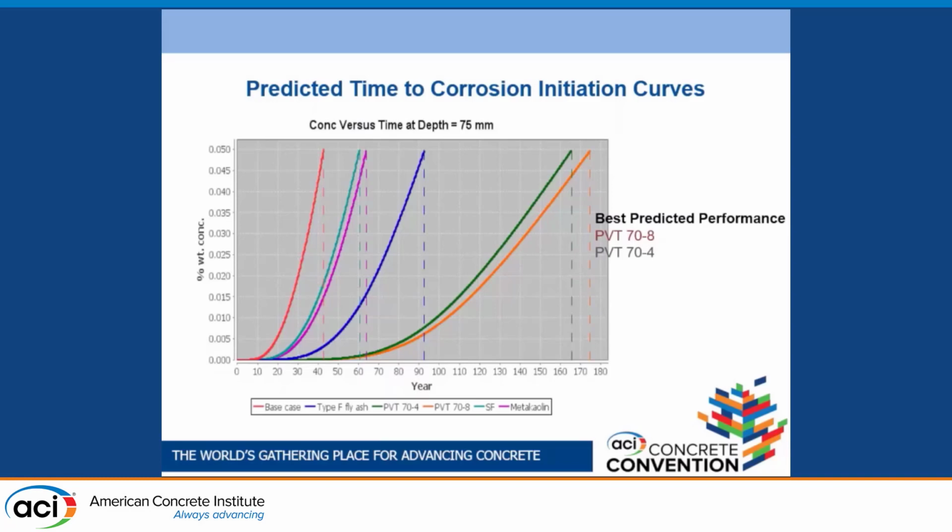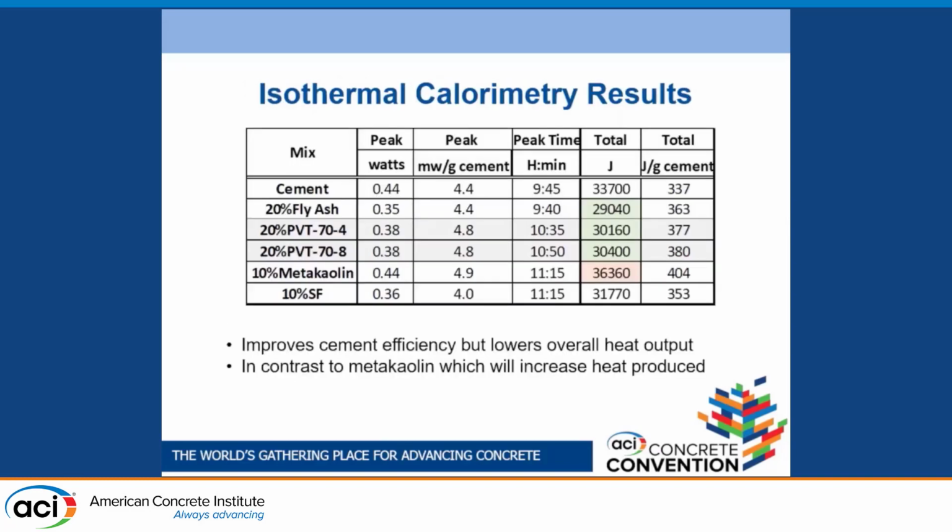Even the Silica and the Metakaolin, because they don't get much better, they'll be better than the control in this, but they don't get you out to a 100-year design life that you might be looking for. Normally, to compensate for that, we might use a more corrosion-resistant rebar or add inhibitors or something. But at least it's conceivable in the model here that these materials, because they do get better in time and start low, can give some good performance.